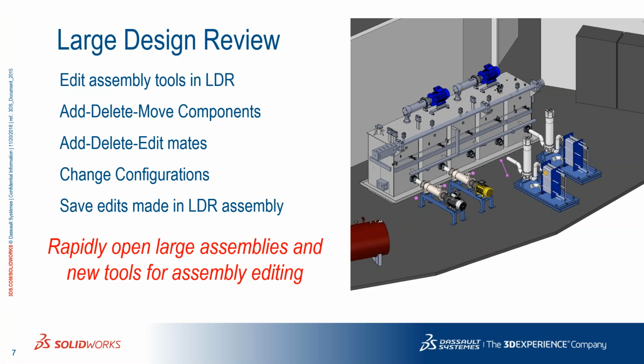The other thing with large design review that I find is that if I have a good size assembly, chances are I'm going to open it up in large design review automatically every time, just because it opens up lightning fast. And a lot of times I'm just digging down into a sub-assembly anyway. So open it up in large design review, right click on a component, open that up fully resolved, and make my edits and do some things there. So large design review, if you haven't used it, it is a great capability if you're working with larger assemblies.